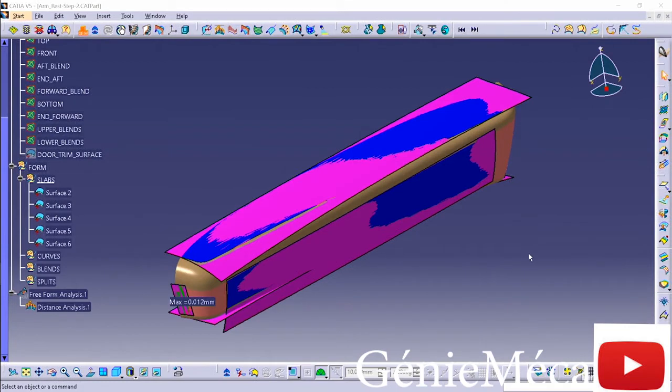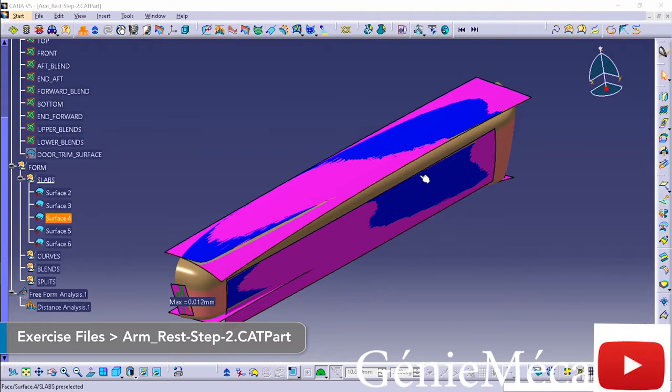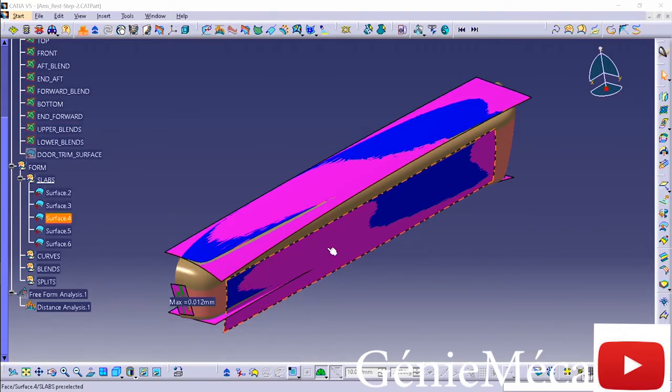Now that I have my initial primary slabs, I need to increase their size. As you can see, they don't quite match to the size of the initial scan. So I have to make them all bigger. And to do that, I'm going to use my Extend tool.